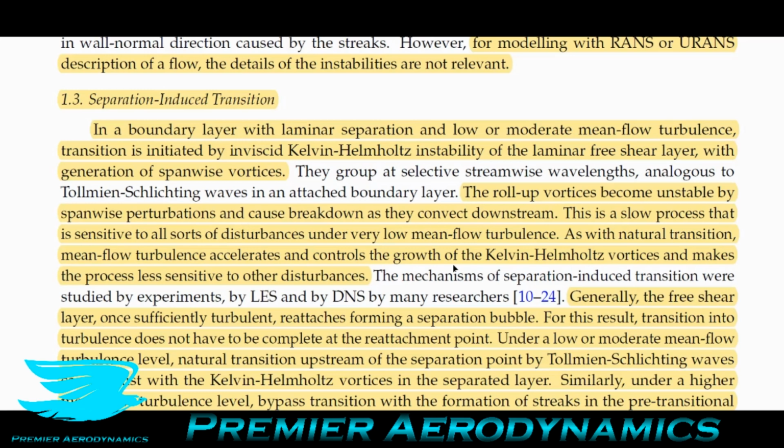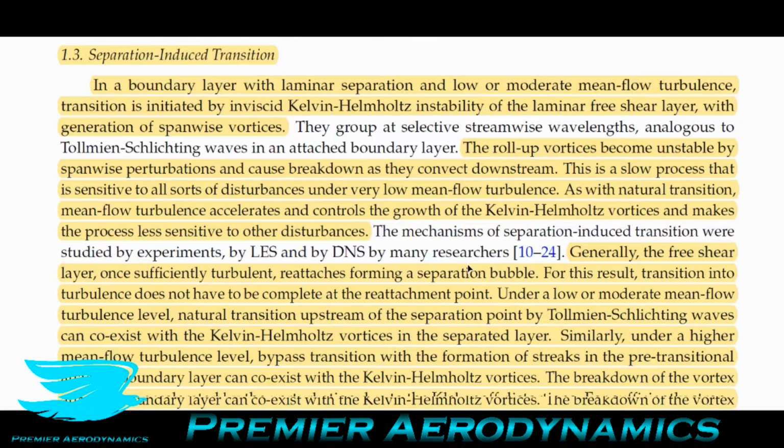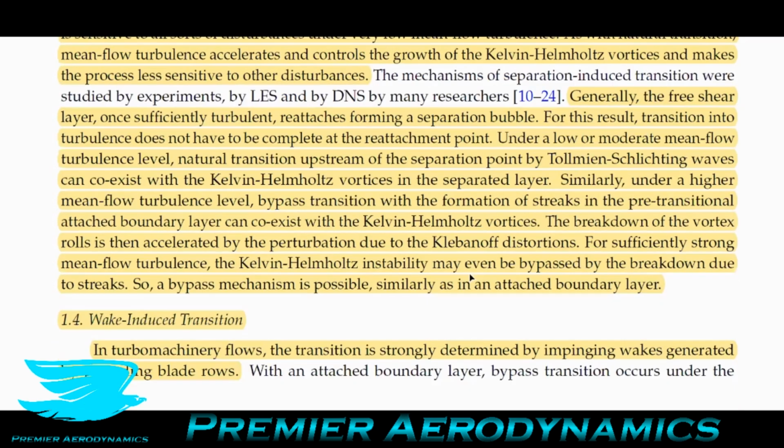The third way is separation-induced transition, which is where we have these LSBs forming. That's where the flow going over a surface detaches. It's still laminar at this point. It detaches, and then the transition occurs while it's detached, and then it reattaches, and it's turbulent now, with this recirculation zone in there. These researchers said that when the flow is attached, it's not necessarily fully turbulent. However, as I mentioned, I haven't seen any data indicating otherwise.